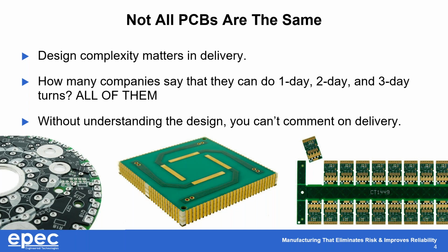Right? If you look at that little part over there to the right, you think, well, that's a really simple little part, or it shouldn't be that big of a deal. Well, it has got staggered gold-plated fingers on it, and it's got a chamfer that has to be done a certain way. So there's no physical way that those boards can be done in 2 days, if you wanted one panel, maybe. Typically in this situation for these connectors, those are usually in the thousands that we do quick turns on.